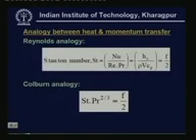Now, let us look at the analogy between heat and momentum transfer. This is very interesting. We have seen that the mass transfer, momentum transfer, and heat transfer by convection all appear to be similar, because all of them have many peculiarities. For example, between momentum and heat transfer, you have a hydrodynamic boundary layer which takes care of the momentum transfer, and analogous to that you have a thermal boundary layer. Because of no slip condition, velocity becomes 0 on the surface, and similarly the fluid temperature becomes that of the surface temperature, again because of the no slip conditions.